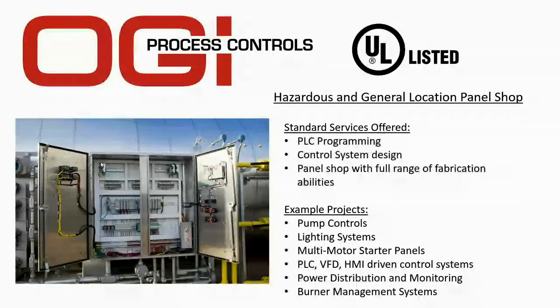That means the QuikWater is actually going to fill up an external tank. And then what we will do, we monitor the tank of that external, we monitor the temperature of that external tank. And if the temperature of that tank actually drops below a preset set point, we will actually recirculate the water from that tank through the QuikWater to bring it up to set point. So yes, it is possible.